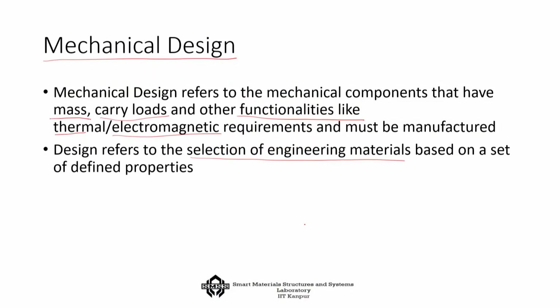But now, for the embodiment of this concept, you have to think about what will be the mass of this system, and that would mean that there will be two types of contributions to mass. What we always say is the dead weight of the system, or the structural mass, that is the mass of the empty bottle, plus the payload. Payload, typically we have borrowed the term from the aerospace industry, means how much additional load, in addition to its self weight, the system will be able to take.